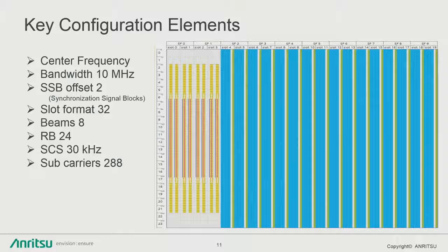I mean, it's possible to do, and I'll walk through that. So you tell the spectrum analyzer, show me only when it's supposed to be off. I'll only know that if I know the slot format, and now I can go look for interference. Okay? That's interference hunting in a TDD world.